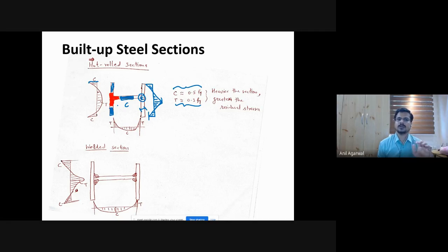Okay, so that part is done. You got the initial part cooling. These blue parts cooled already, and now they have solidified. They have become harder now. They are stronger, and your red part is still hot and soft. At that time there are no stresses, because this red part was not able to offer any resistance when the blue part was shrinking. Fine. So there are plastic deformations, but no stresses.